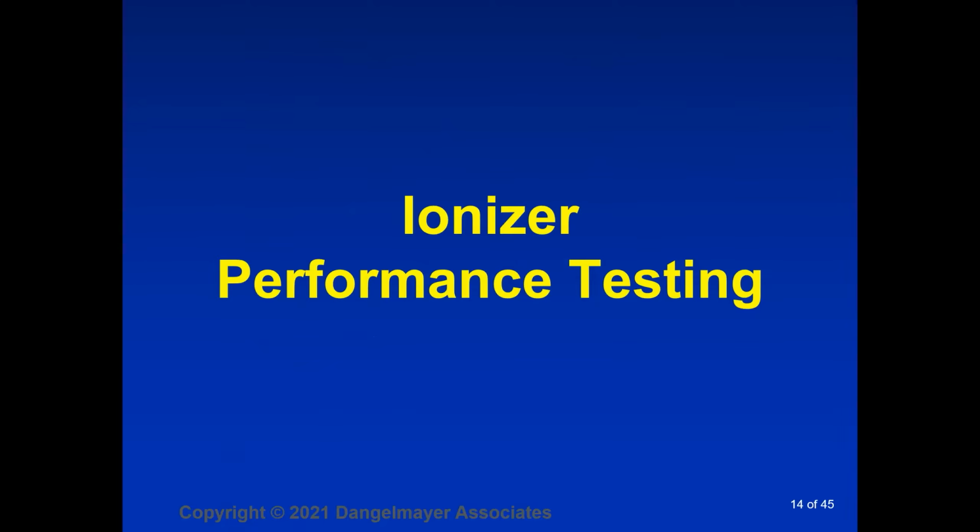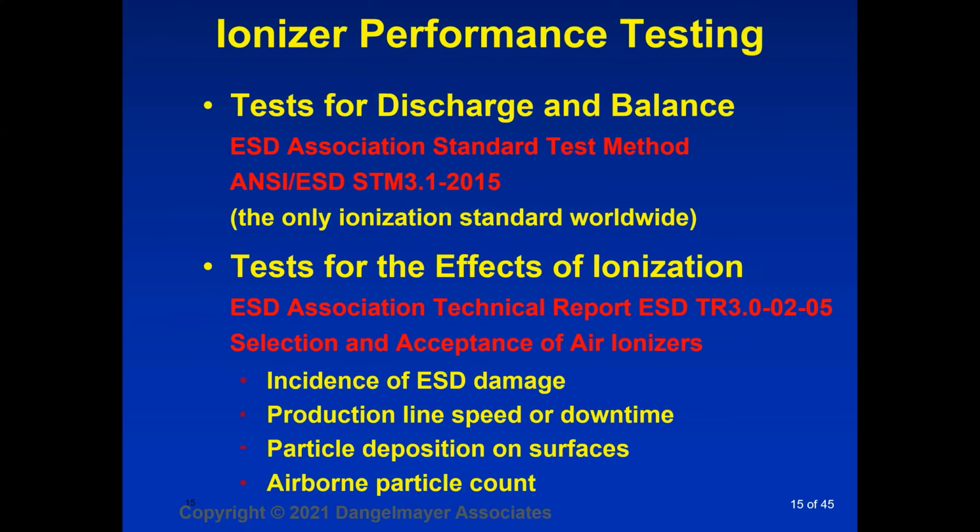You need to test the ionizer to see how well it neutralizes static charge. So again, fortunately, we have documents at the ESD Association that will help you do this. The document we're talking about now is STM 3.1. Its last issue was 2015, and there probably will be another issue very soon of that document. It is the only ionization standard worldwide. Everyone worldwide uses this document for testing ionizers.